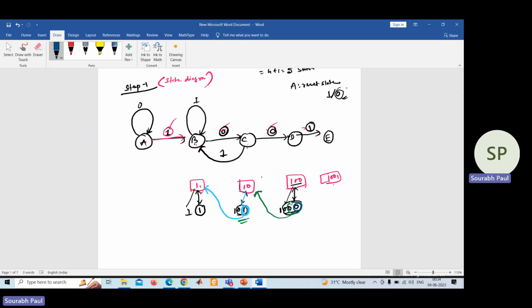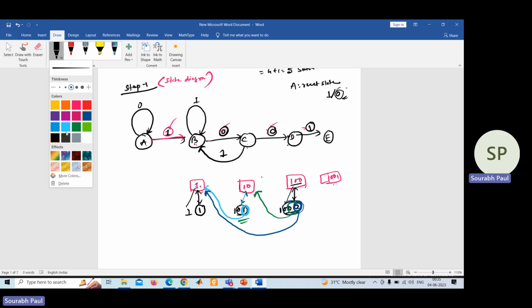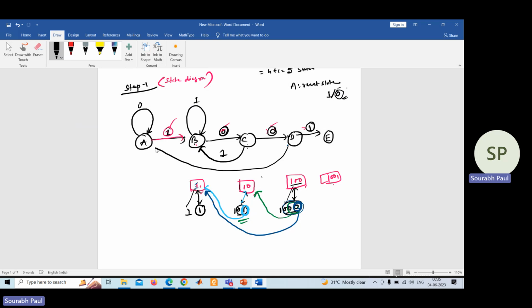If you can remember from where you have started, we have considered first 3-bit. We have compared with the 3-bit state. It doesn't match. Then we have taken the right side 2-bit. We compared with the 2-bit state. It doesn't match. Now we have 1 bit, and that is the extreme right side bit, that is 0. As it is a single bit, you need to compare with the single bit state. Is it matching? No. What is the single bit value? That is 1. And here it is given 0. Are they matching? No. So what do you need to do? You need to come to reset state. So go to reset state. So D goes to reset state and your input is 0.